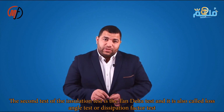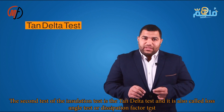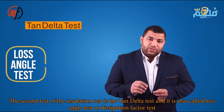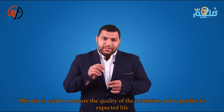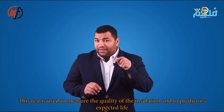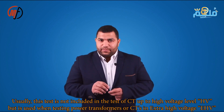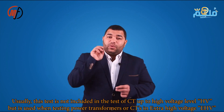The second test for insulation is the tan delta test, also known as the loss angle test or the dissipation factor test. This test is used to measure the quality of insulation and predict its lifespan. Usually this test is not part of the site tests, but is included in the power transformer tests.